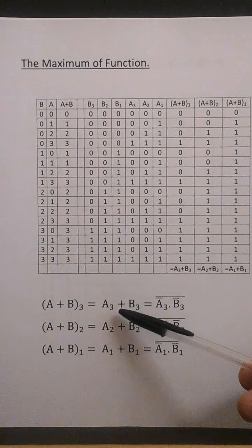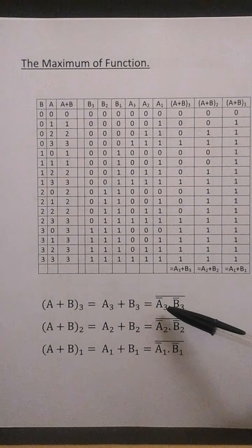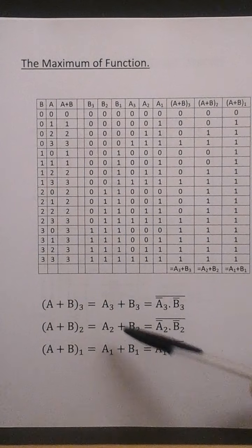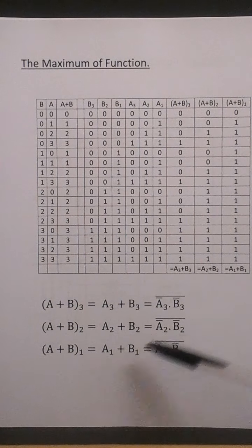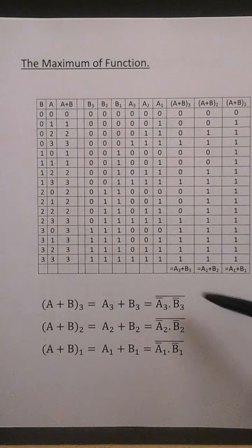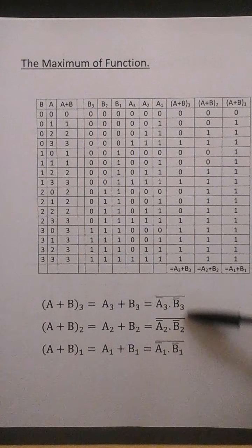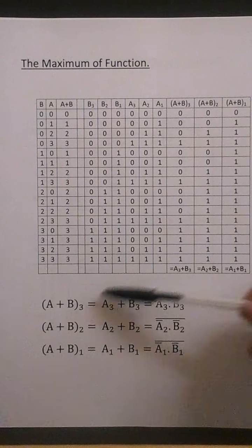Again, I'm going to change the OR function into a NAND function here as well, just for the same reasons, just so I can get away with using 6 Schmitt trigger inverters instead of 12.